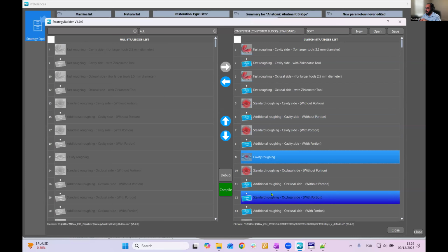In theory, you can start with a finishing before roughing. That will cause you a problem because that area is not roughed yet, and you start directly with the finishing, it will hit material, it will cause a tooth break, depending on the material that you have. It might damage your spindle, like if it's titanium, for example.